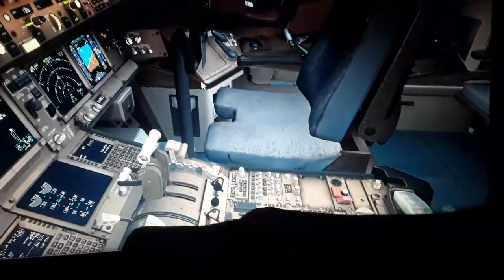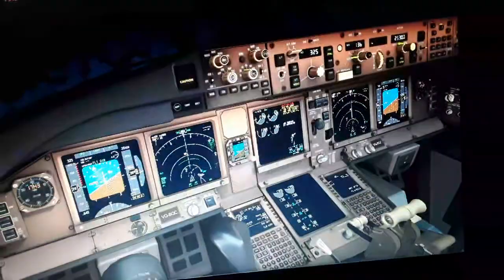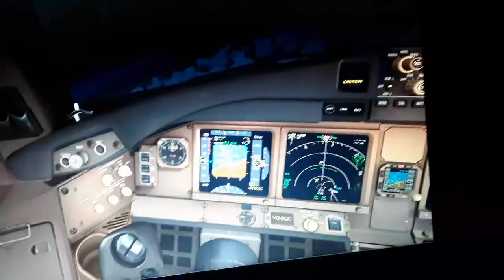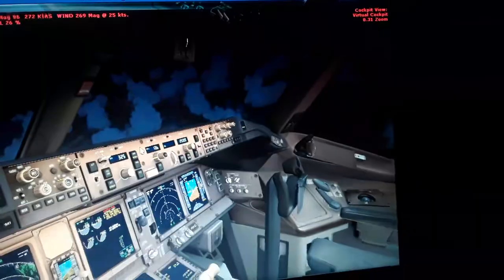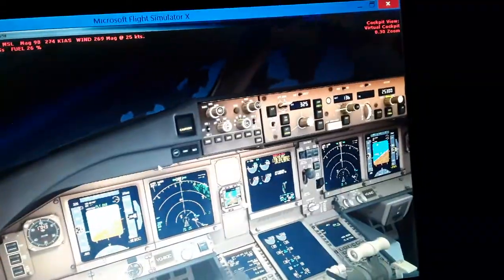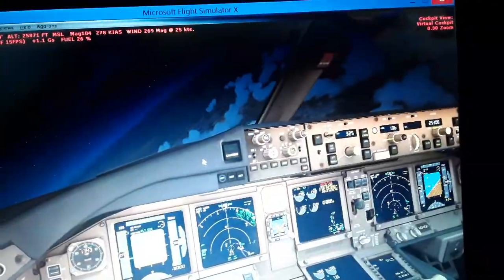So we take the turn manually, having higher airspeed, and also retract the flaps here. We don't need so many flaps, so this is going to give us higher airspeed. You can see here we have the stall speed we need to avoid while we increase the airspeed while we're taking this turn. You can turn more, a little bit more bank angle.